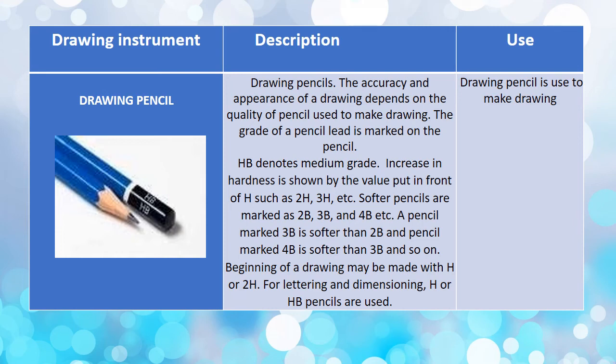The beginning of a drawing may be made with H or 2H. For lettering and dimensioning, H or HB pencils are used. Its use is for making drawings.